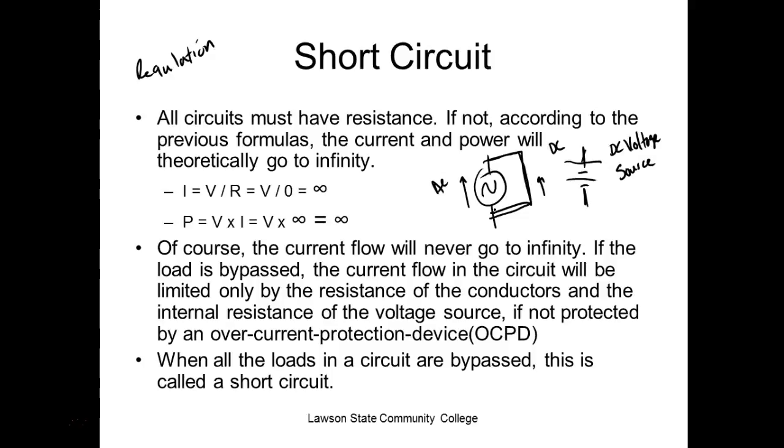So somebody's going to give up. So what happens? Somebody gives up. Now, if you've got an unregulated source, it's usually the voltage source that gives up. So I could come up here and get a AAA battery and take a wire and put it across it, and the output of the battery goes down to 0. Because now the internal resistance of the voltage source gives up.